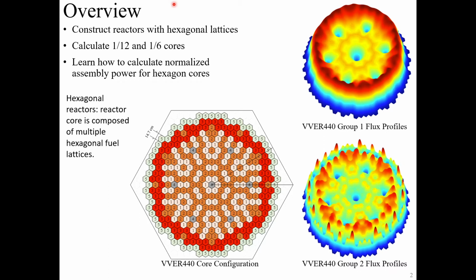While applying boundary condition, PDE coefficient, and post-processing are quite similar with the rectangular reactor modeling. In addition, you need to learn how to cut the reactor to 1/12 or 1/6 to take the advantage of the symmetry.